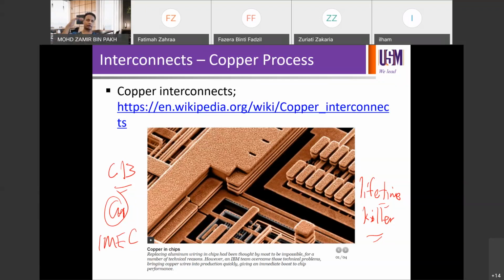We ran hundreds of test wafers through the system after the decontamination process, and then we had to go for TXRF measurement. It's one of the characterizations available in the fab. Total X-ray fluorescence. It will detect metal contaminants on the wafer. If you have contaminants on the wafer more than certain levels, out of the spec or beyond the spec limit, then you cannot release the equipment to run mass production of non-copper lots.